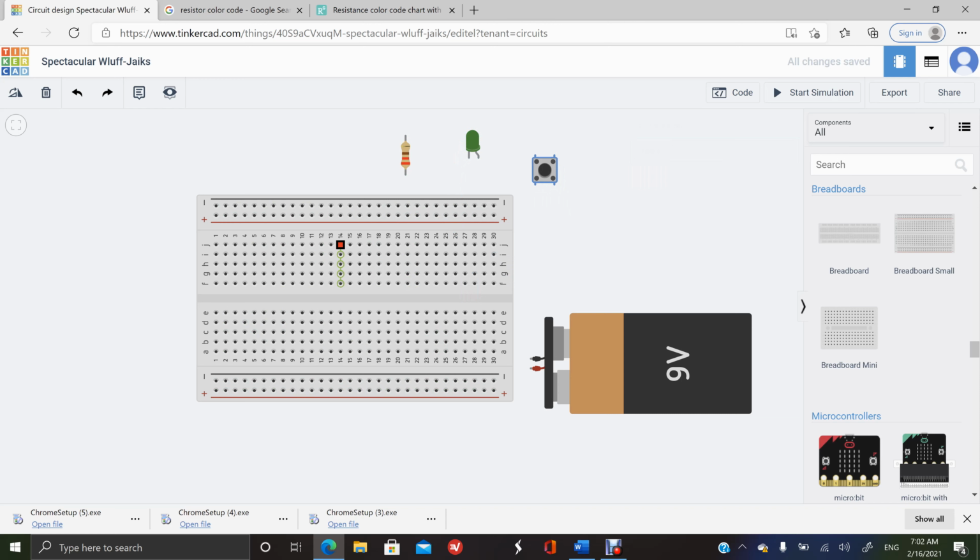So the breadboard basically is nothing but a piece of plastic board with holes. And you see, when I click on one, for example, this column here, you see they're all green. Okay, means all these five, how many of them? 1, 2, 3, 4, 5 holes, they are connected together. So the same thing here. These are connected, but they are not connected to the other ones. So each column is connected. Each hole in the column is connected. There is a metallic clip in the bottom that connects everything. The same thing goes for here.